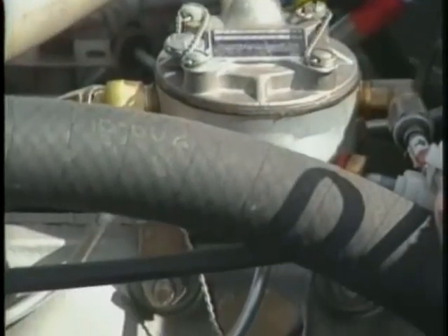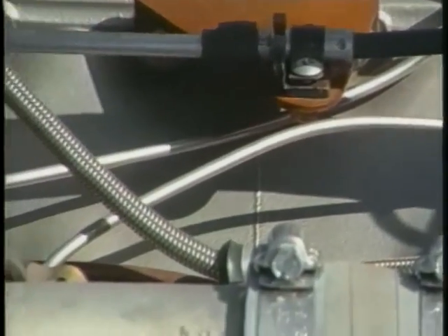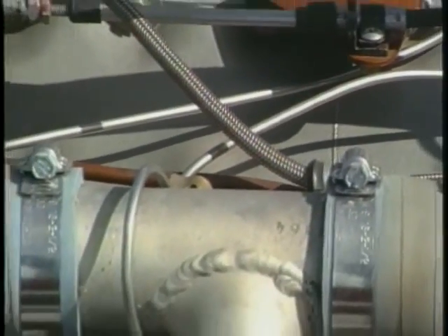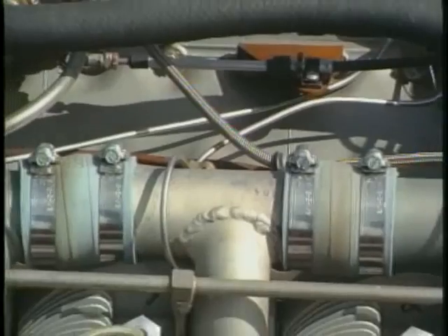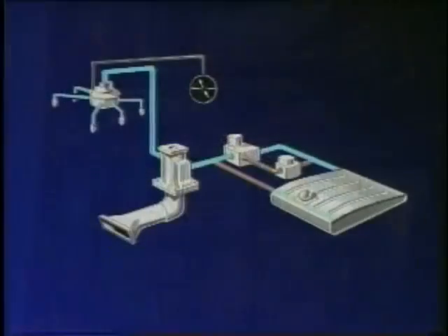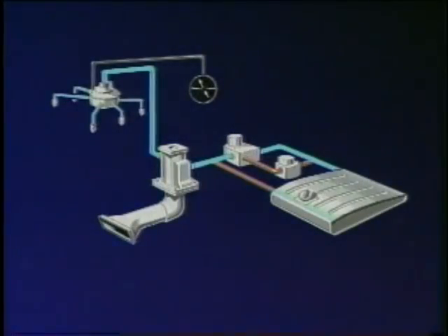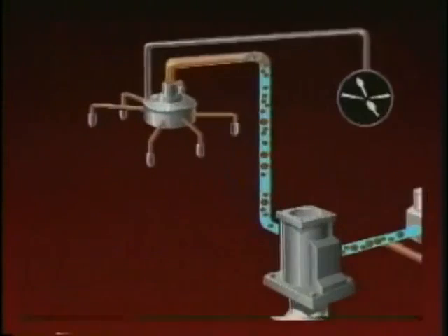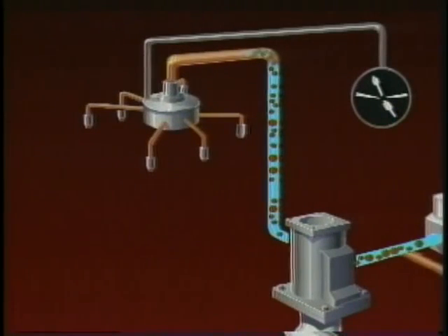The reason fuel injection systems are more likely to experience vapor lock is because there are more fuel lines in close proximity to the engine and the heat it produces. If temperatures are hot enough, the fuel inside the lines vaporizes, resulting in low fuel pressure or engine failure due to fuel starvation.